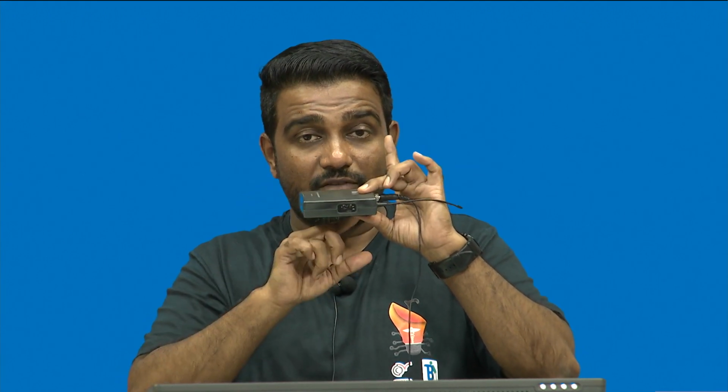But if I want to create a diaphragm, let me give you an example. If this is the wafer and this is the sensing area, I want to create a diaphragm exactly on the back side of this sensing area. That means I should align it on this side. How would I know it is perfectly aligned with the front side? That is what is called front to back alignment. I want to create a diaphragm exactly below this particular sensing area. This is where your front to back alignment will work. We will take an example in the next module. Till then, you just go through these slides.